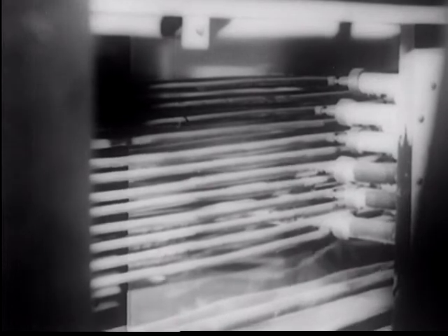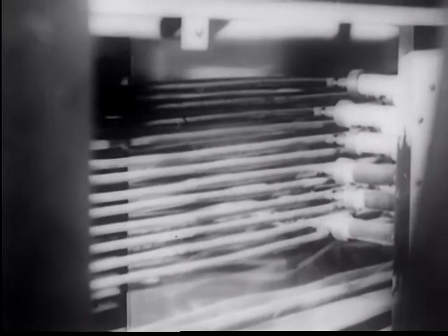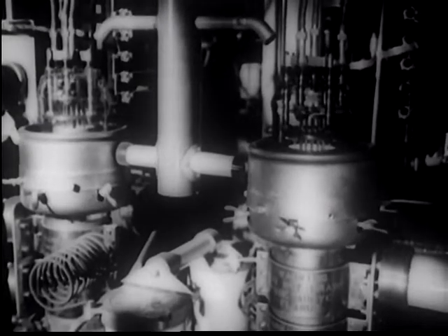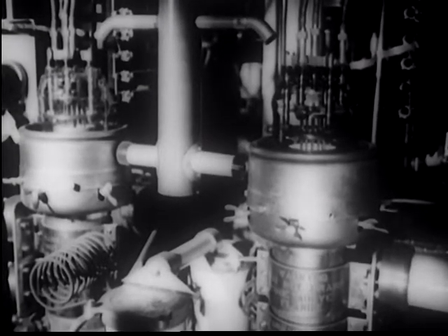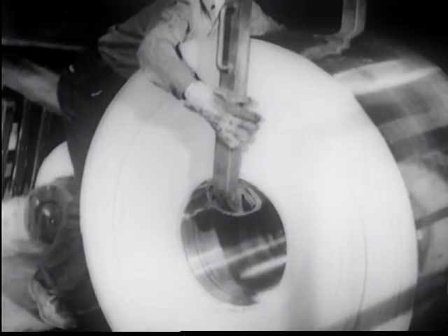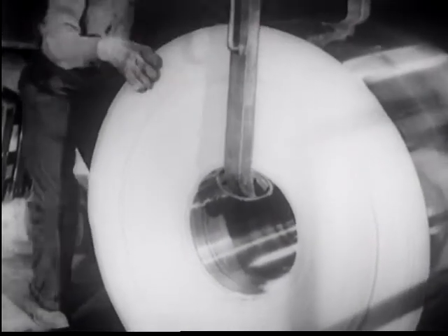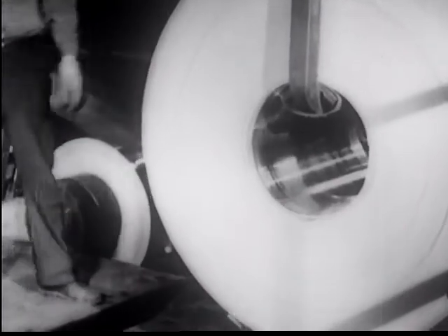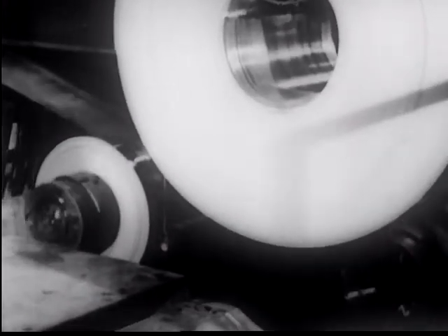Note the horizontal bars in this close-up. These are parts of one of the high-frequency coils that affect the tin flow. If you look closely, you can see the difference in texture between the porous tin entering the top of the coil and the shiny flowed tin leaving at its base. And these are the tubes that generate the high-frequency current which makes the entire process possible. Another important result of this new Westinghouse electronic process is time saving. Tin can now be flowed at a rate of more than 1,000 feet a minute.